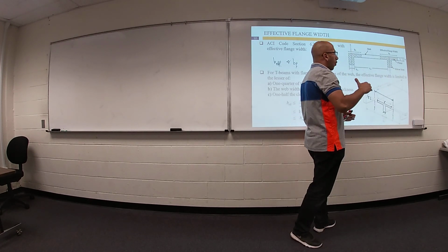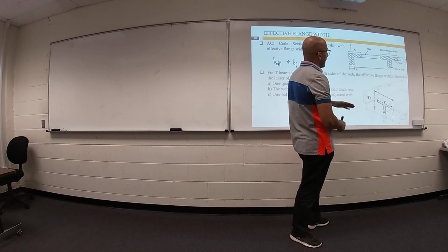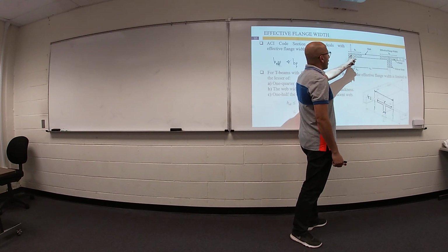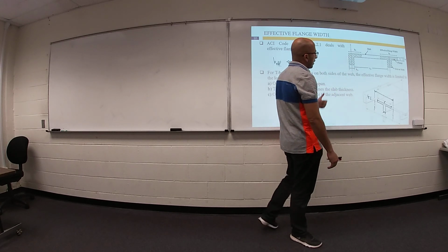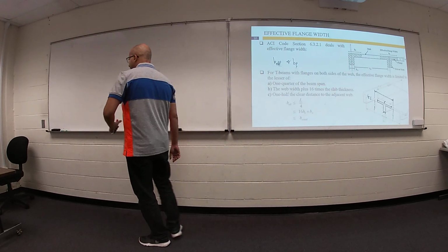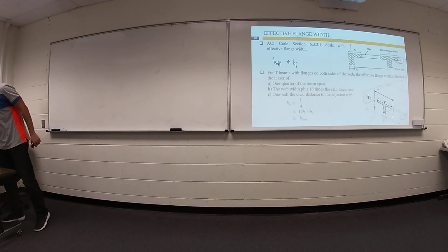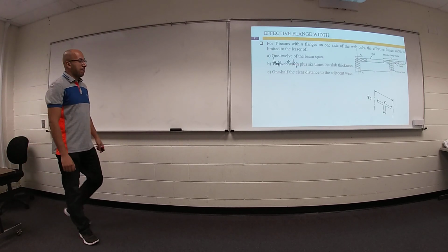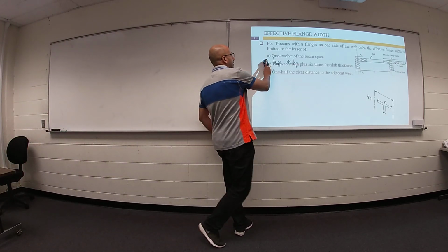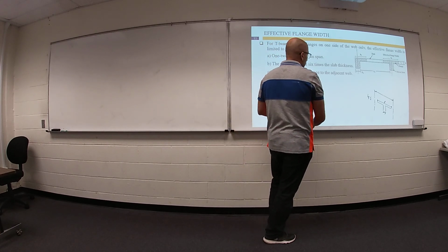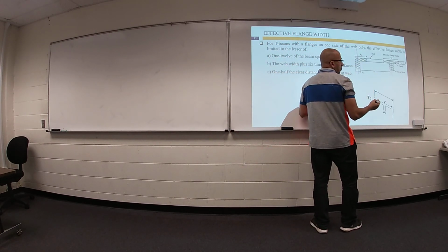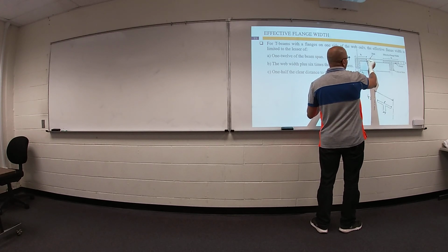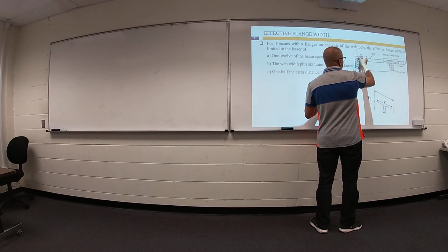Sometimes your beam called edge beam at the edge of your building. So we have only one slab or slab from one side, nothing from the other side. So in this case, we have different values for your B effective. Your B flange will be something like this. And your cross section, not T section, but L section, looks like this.